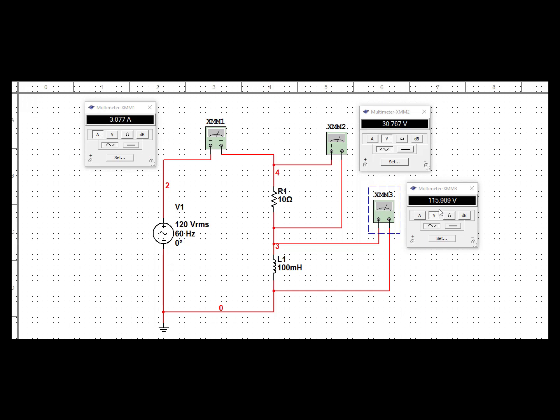Now we had our 116.1, but don't forget we used a little bit of a rounded up current, and the value that we used to calculate our angular velocity was not exactly the 2 pi f value. We used 377 for angular velocity, which is generally used for 60 hertz. But there's certainly no worry in these results. They're confirmed by our calculations and our analysis, so we're happy with that.